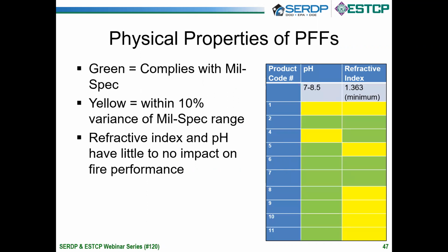Now, if you look at the mil spec, this is a performance-based spec, but you find with a lot of old mil specs, other specs that are several decades old, that some properties really describe the physical properties of the products, and they really don't relate to the performance criteria. For example, the pH and refractive index really have little to no impact on fire performance, but these are there.